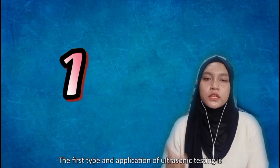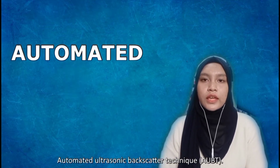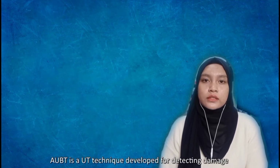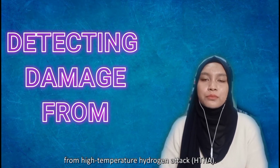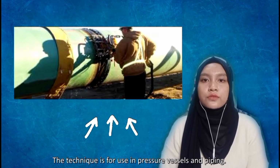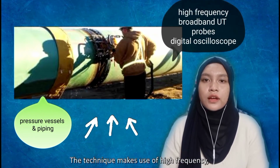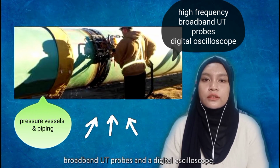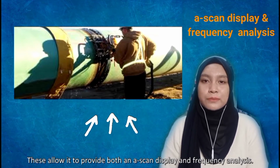The first type and application of ultrasonic testing is Advanced Ultrasonic Backscatter Technique (AUBT). AUBT is an ultrasonic testing technique developed for detecting damage from high temperature hydrogen attack (HTHA). The technique is for use in pressure vessels and piping. It makes use of high-frequency broadband ultrasonic testing probes and a digital oscilloscope. This allows it to provide both an A-scan display and frequency analysis.